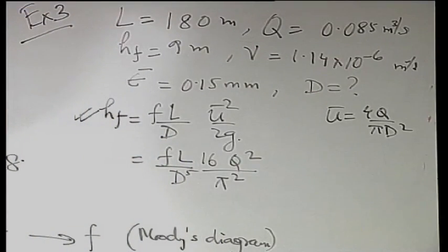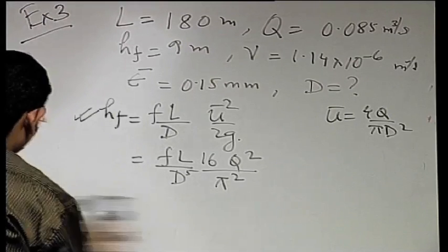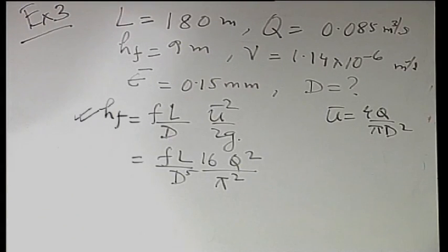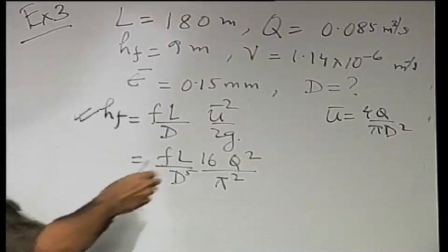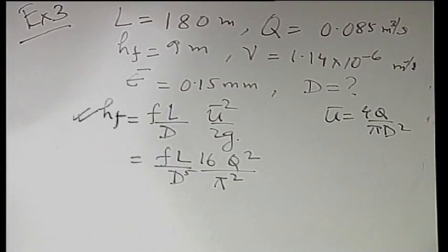So when hf is given, then what is the next thing that you should do? If you know Q and if you have an estimate of what is hf, which is already there, you can find out what is the friction factor.